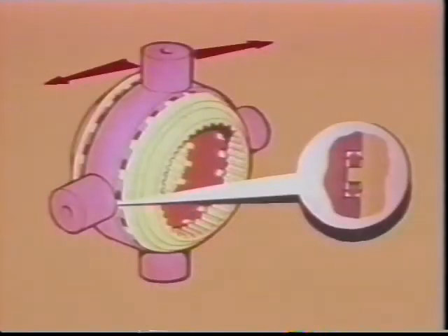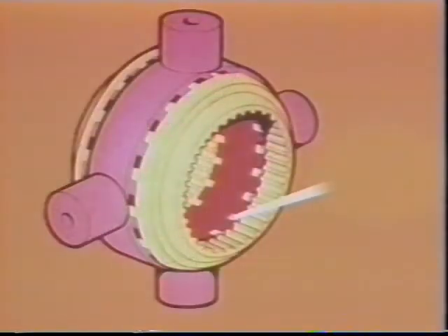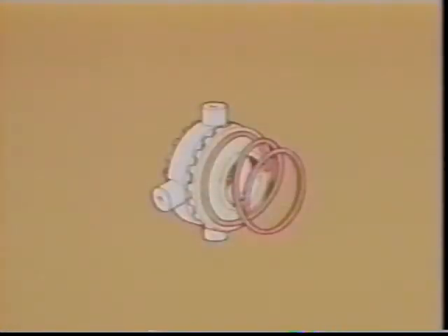If the two driven clutch members are held against the cross and center cam assembly, only the cross will move back and forth in the gap. The center cam, which is allowed to turn inside the cross, is held by the inner row of teeth of each driven clutch member. A return spring sits on the shoulder of each driven clutch member. A spring retainer sits up against the flange of each side gear. When the spring is compressed, the splined side gear fits into the spline-driven clutch member.